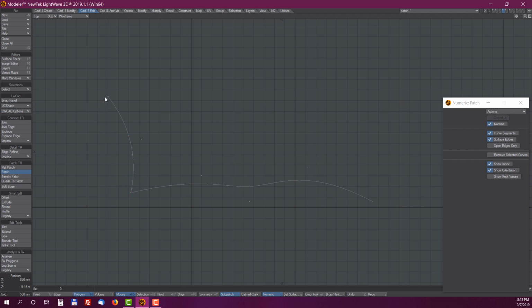So for this case, railing a segment along a single curve, you have to click from the opposite side of the railing curve to define direction this way, and then the second selection of the V railing curve doesn't matter because it is already aligned to fit the original selection.